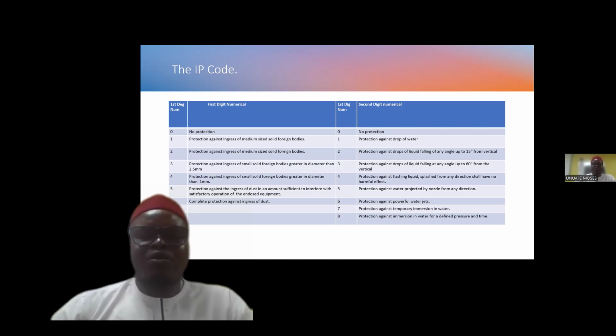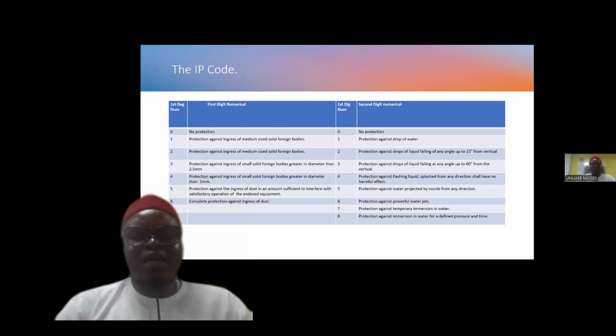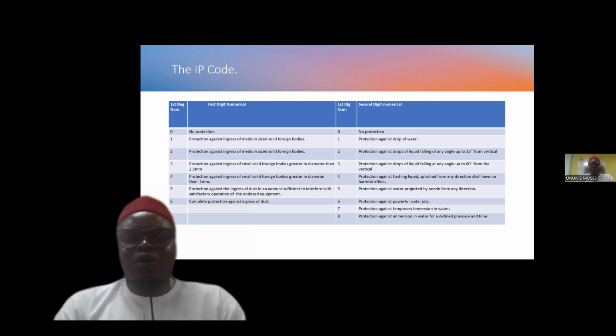That is to say, whenever you are selecting equipment for installation, look at the nameplate very carefully and select the IP rating that matches that particular environment, especially in an installation of equipment outdoors, on the field. So, therefore, a proper selection of IP rating will guarantee effective operation and efficiency of that equipment and enable the equipment to work in that environment safely.